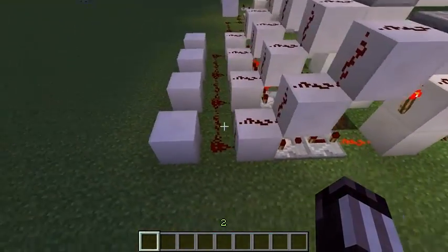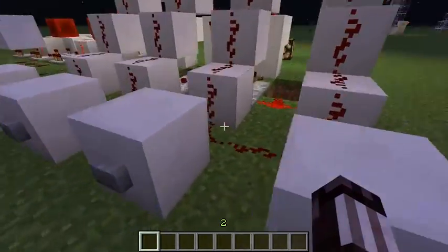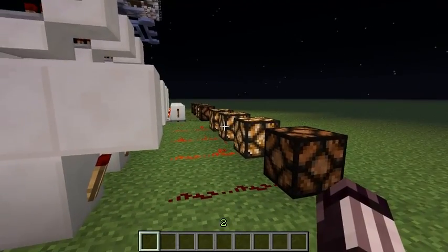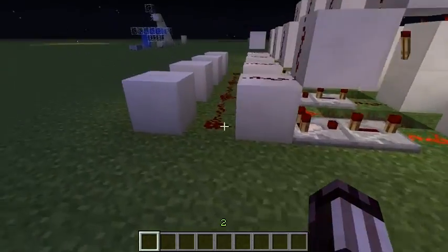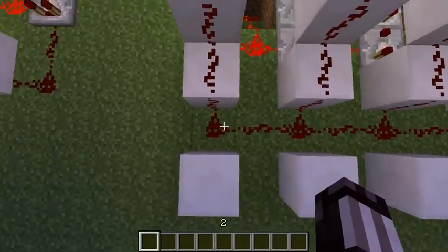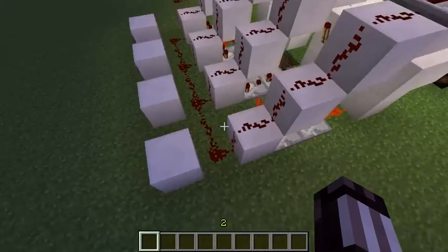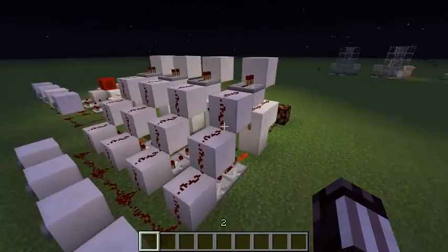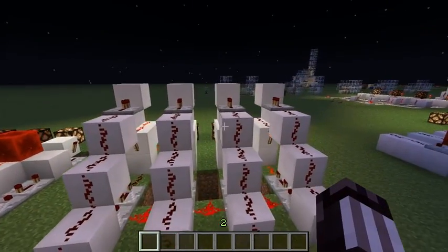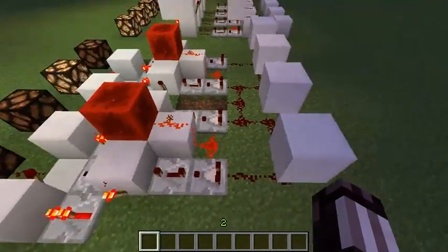And first I need to reset all the latches, because if I won't reset them it will just add an option, but I need to select options, and that is why I'm using a bus here. But because I'm using the single bus to send the signal to the option, I may use it to reset the options as well, so I don't need to hook up the second wire that will come through all these RS NOR latches. And this is the attempt of minimizing it.